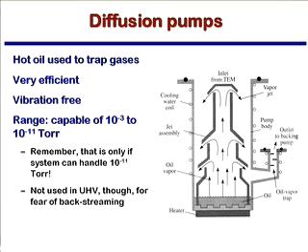The idea, again, is that these oil molecules are condensing down and knocking the gases down physically via kind of an interaction through here. Now, the thing about the diffusion pump is, again, it's oil-based. And so if for some reason you screw up the vacuum order, right, you hit the wrong button in the wrong order, and you put a positive pressure here with respect to there, you can have oil go back up into your system. This can be disastrous, and as a result, most of the systems that use these diffusion pumps do not let you do anything with the vacuum other than initiate it, okay?